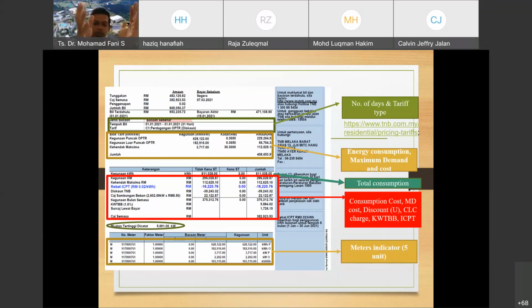The 5,000 kilowatt peak is a 1 second peak and is not maintained for 30 minutes, so we will not consider it as the maximum demand. The maximum demand is the largest power within the 30 minutes.